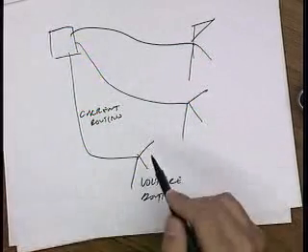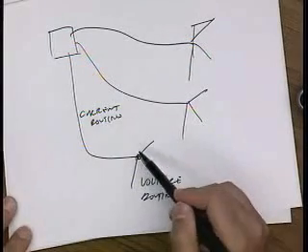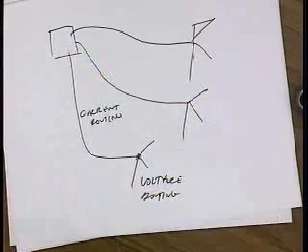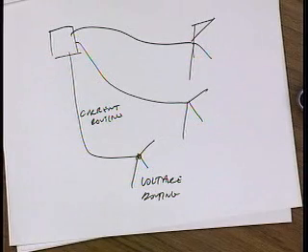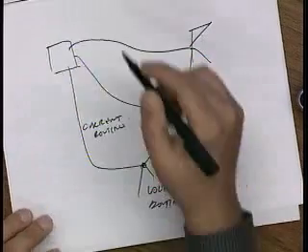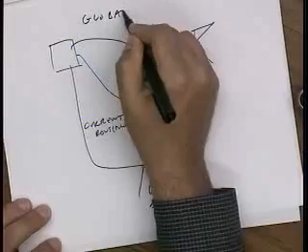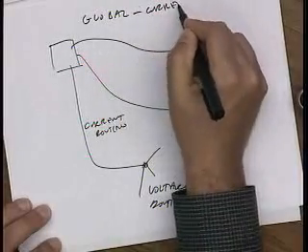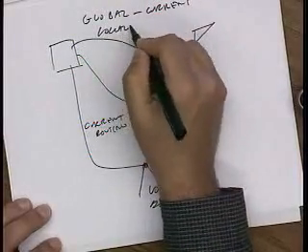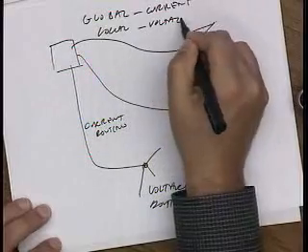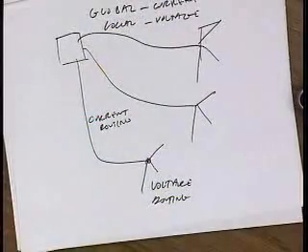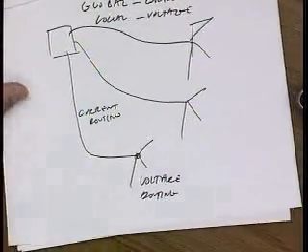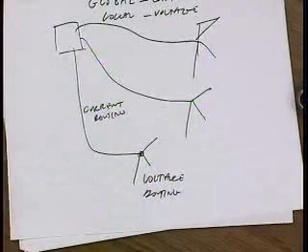And you do the current routing so that you're not sensitive to threshold voltage variations, and then locally you can do voltage routing. Okay? So global, current, local voltage. All right, so that's a little bit of a detour, but I think it's an important detour. So let's get back to the lecture.